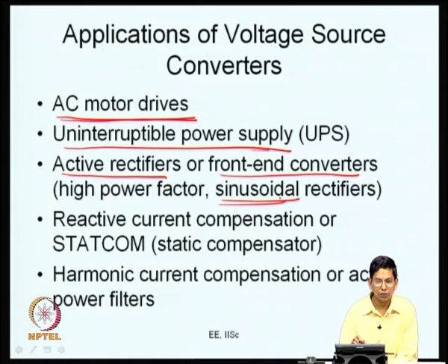As we saw, the fundamental current is being controlled and the harmonic voltages are there, but they get filtered out by the line inductors, so the ripple current, the harmonic currents, are much lower in amplitude than the harmonic voltages, and the currents are near sinusoidal, with power drawn at a high power factor. So, in the active rectifier the power factor is controlled to close to unity. Rather, you can make sure that the power factor is not unity, but 90 degrees. The current is leading the voltage by 90 degrees.